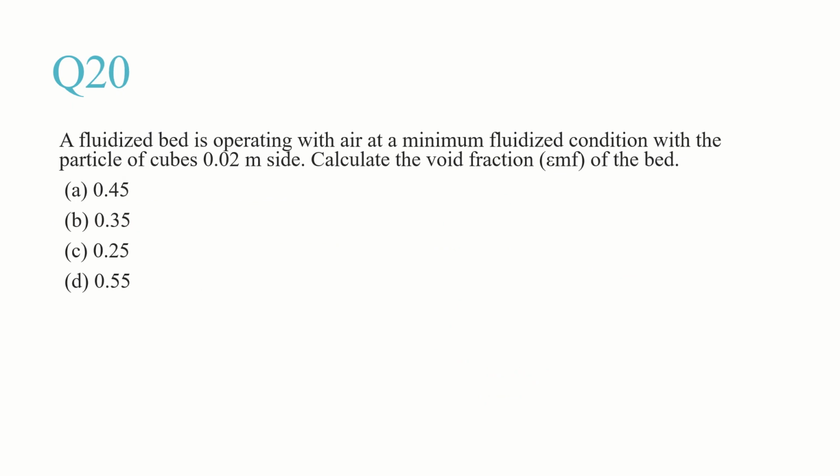And okay, a fluidized bed is operating with air. This question is an incomplete question actually. But for cubes, the packing fraction is around 0.6. A fluidized bed is operating with air at minimum fluidized condition with particles of cube of 0.02 meter side.